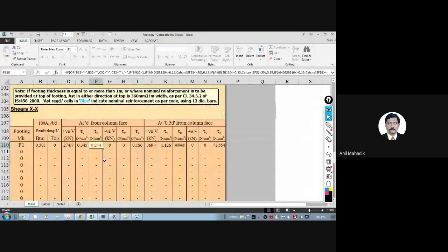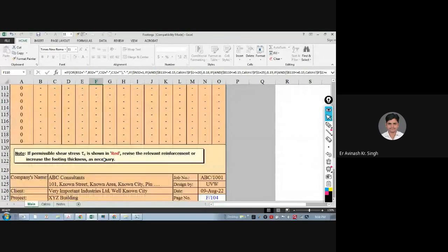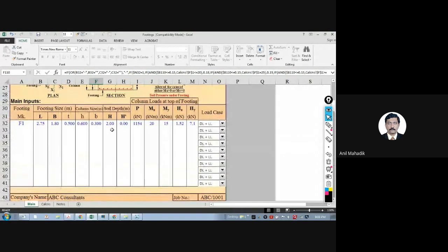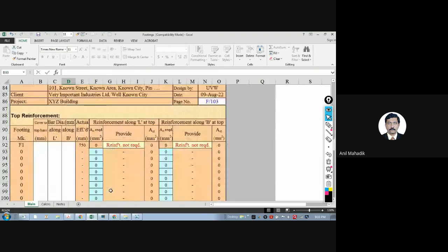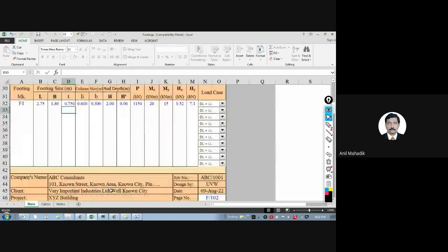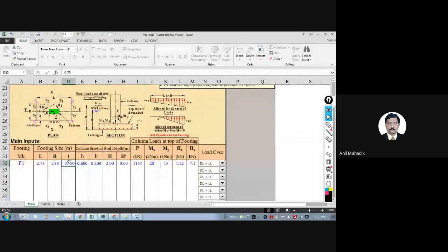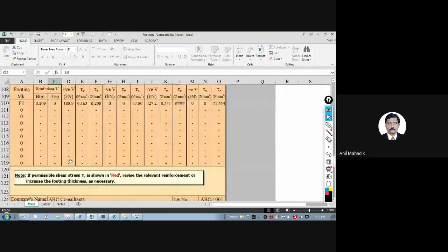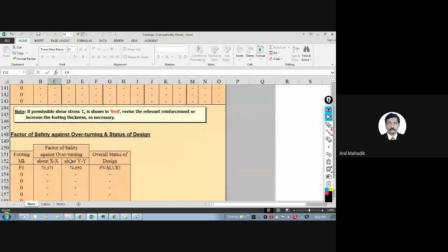Shear stress is not satisfied. What to do? Depth required is to be increased. So what was our depth? We will change 0.5 to 0.75. Is it okay? Still try 0.7, because we should optimize too. After it passes, don't stop, try to optimize. We made it 0.7 and it is working. Even you can try 0.65, and that is up to you. You can try many times.